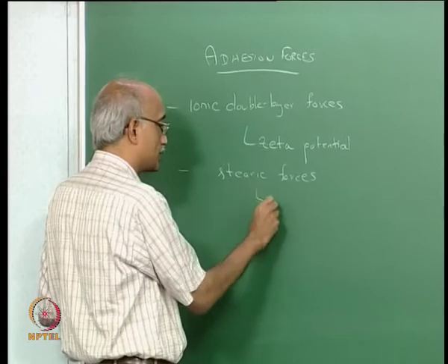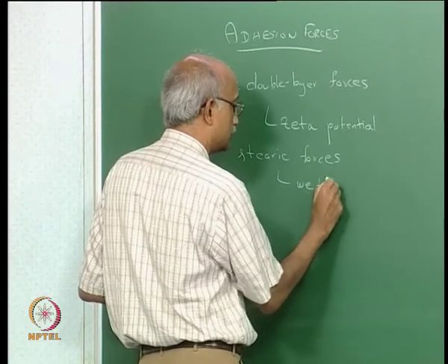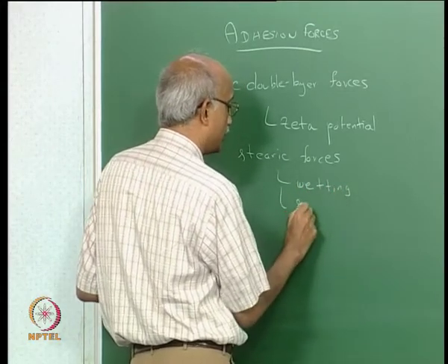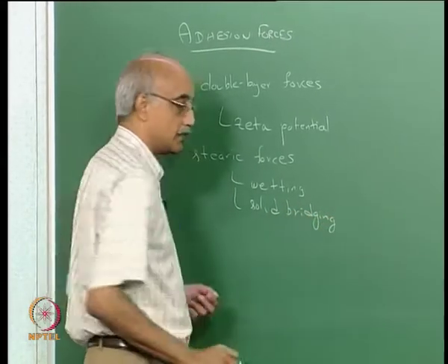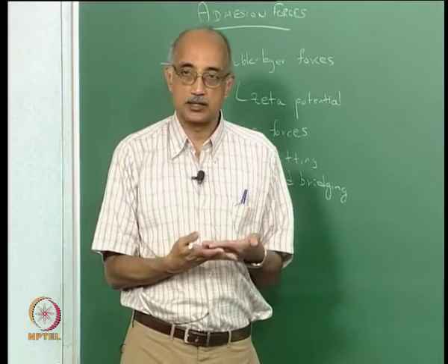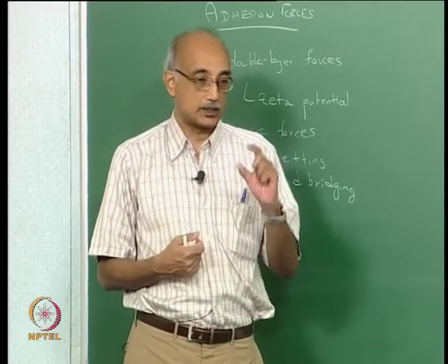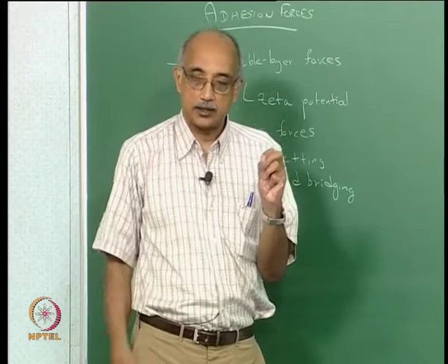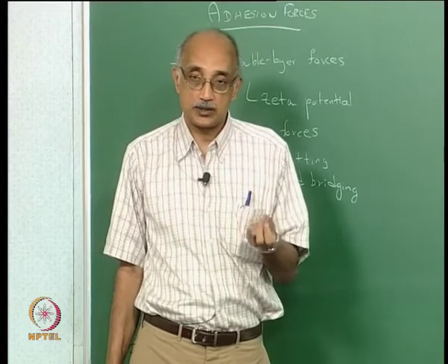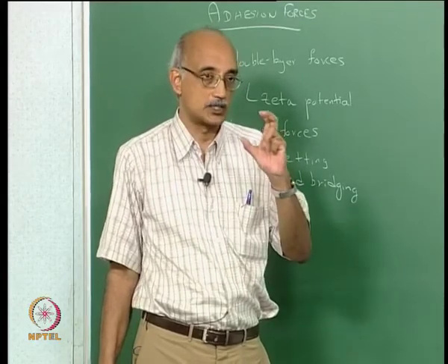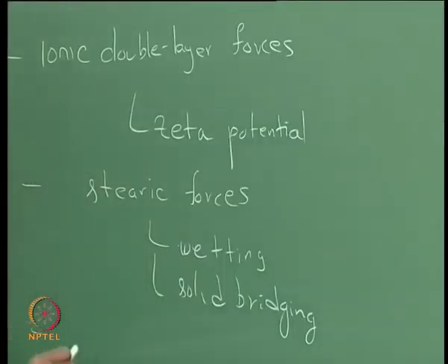When we talk about steric forces, again they can be subclassified as wetting and solid bridging forces. When a liquid first wets the interface between a particle and the surface and provides an additional adhesion force, that is called a wetting action. Now, if you take that same interface and you dry it, then the adhesion force actually increases by several orders of magnitude, because the liquid that is trapped between the particle and the surface now solidifies and actually forms a solid bond between the two. So, that is called solid bridging.